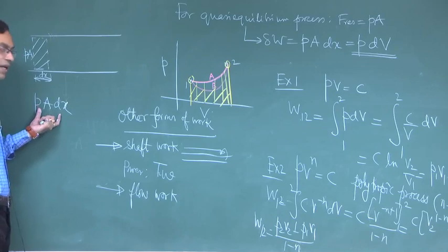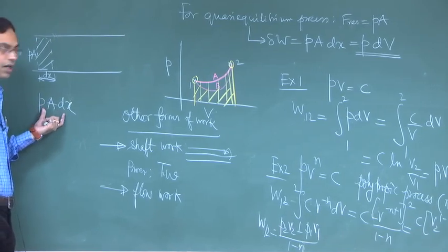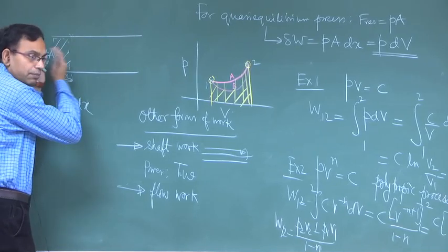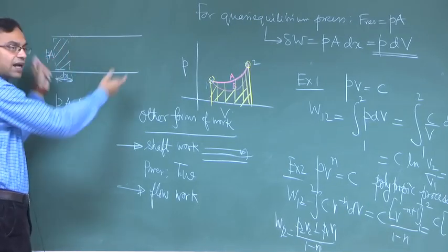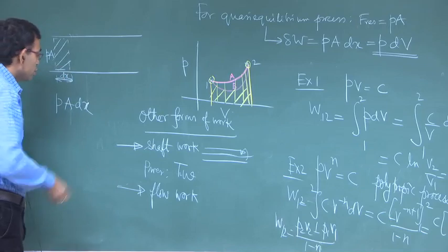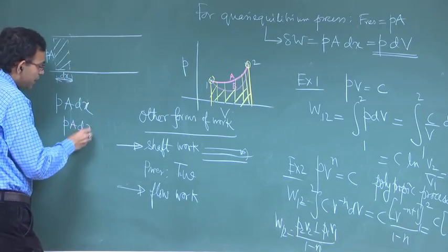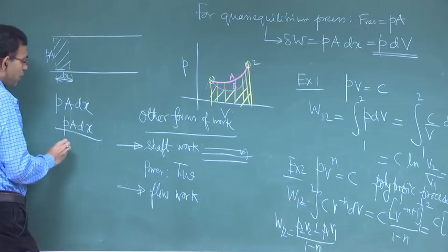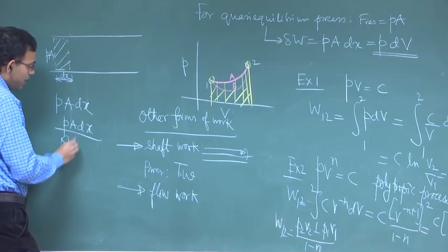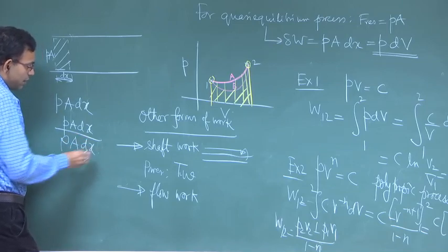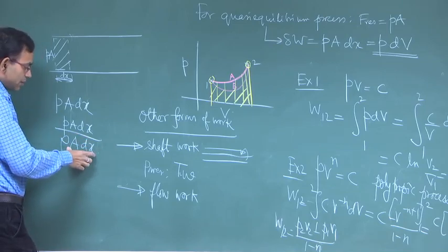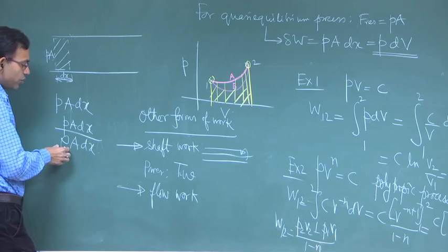So, this much energy the fluid must have to maintain the flow in presence of pressure, otherwise it cannot displace this and make the fluid move, it will be a stagnant fluid. So, this work per unit volume or per unit mass, A into dx is the volume, that into rho is mass.